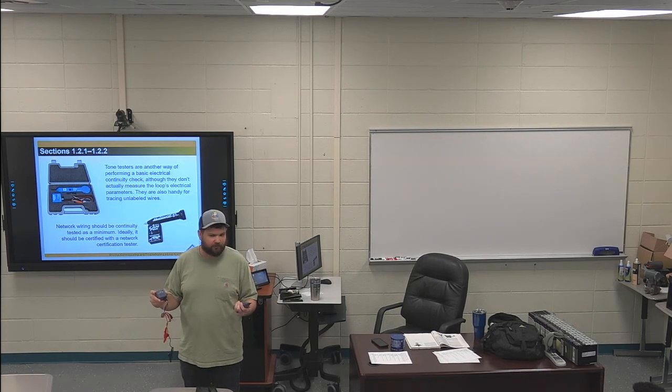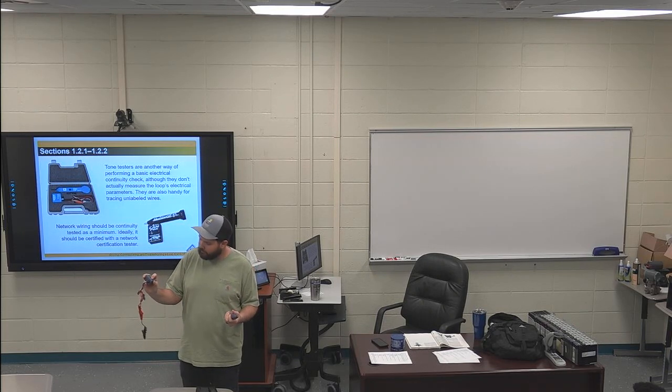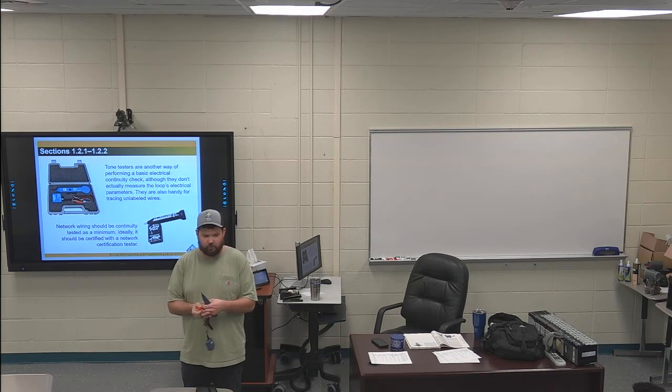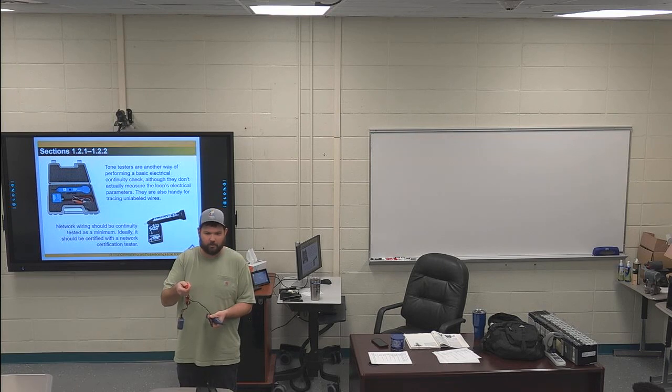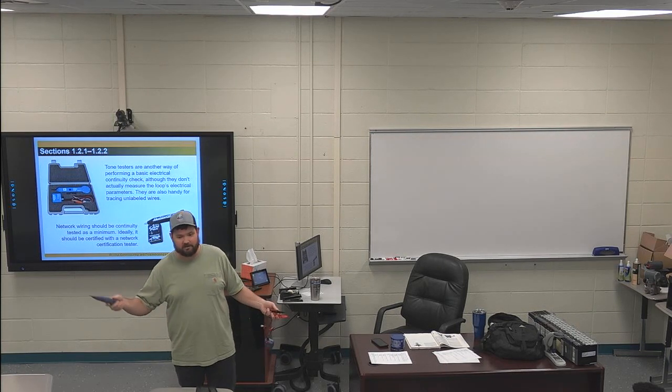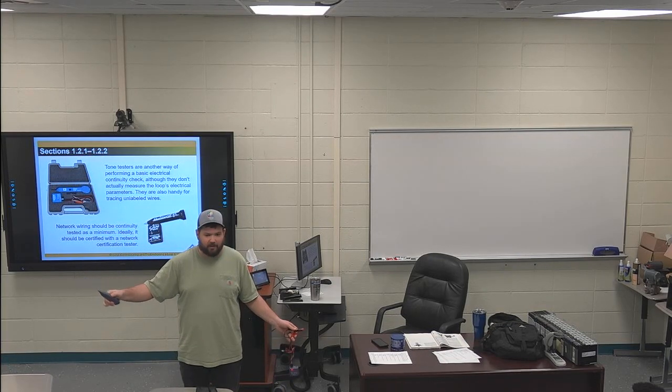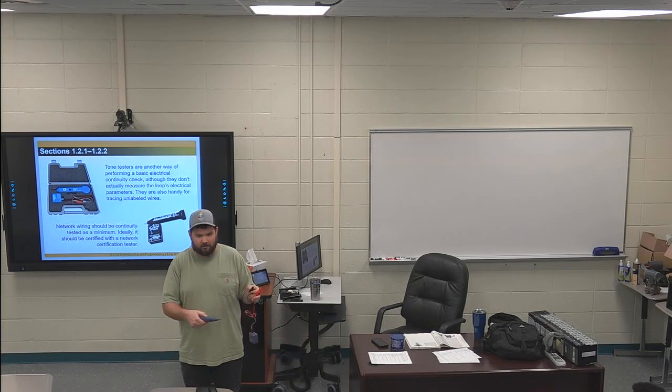I use these for finding wires that I don't know where they go. So I can turn this on tone, and then you would connect this to 2 of your wires, one to ground, one to whatever wire you're searching for. And this thing can check through walls and stuff, or getting close to ceilings. I just push my button, and whenever I get close, you can find which wire you're talking about.